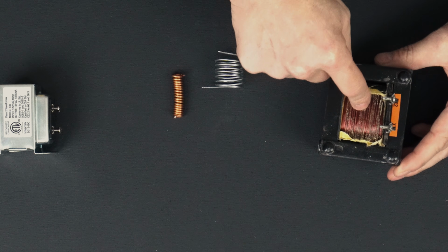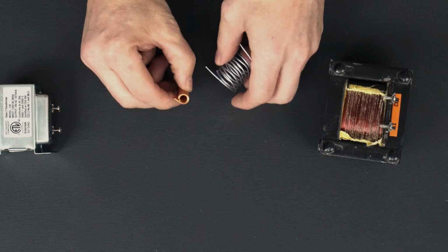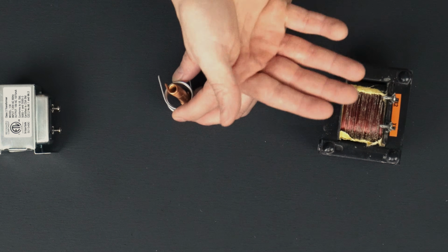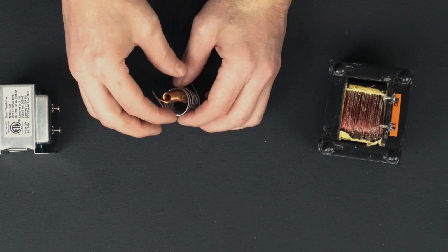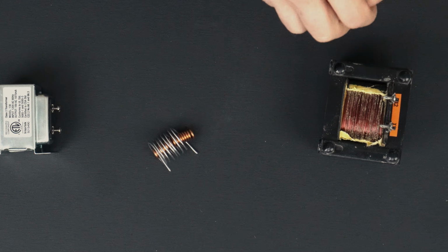So these are both wrapped, the inner one's wrapped around that bar in the middle, and then they just take another winding and they wrap around that. There's an insulative layer in between them, so that they're actually not touching each other, but it allows you to wrap 2 different coils around one common iron core, and that iron core is going to strengthen those magnetic fields, and the transformer is going to work a lot more efficiently.